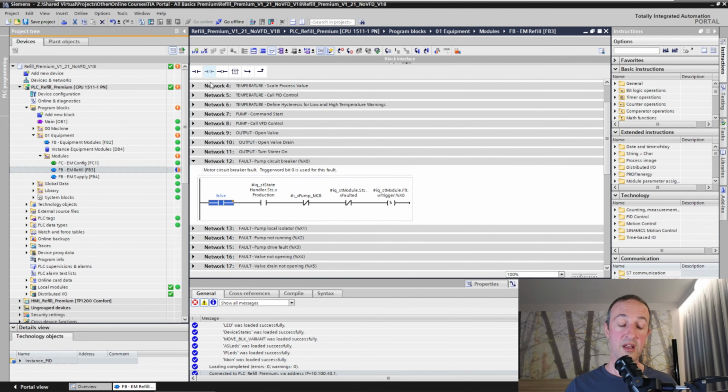What I would suggest is you actually create a commissioning bit, or you even make a DB, where you call it DB commissioning, where you add your commissioning bits. This way, they're very easy to find using the cross-reference. So for commissioning, never just put a false in front. This is purely as an example, but this is not how I would do it in the real world. In the real world, I would use a flag that's very easily traced back, so I can take them out of the software afterwards, and you're not left with any commissioning bits or rungs that are disabled after you're finished commissioning.